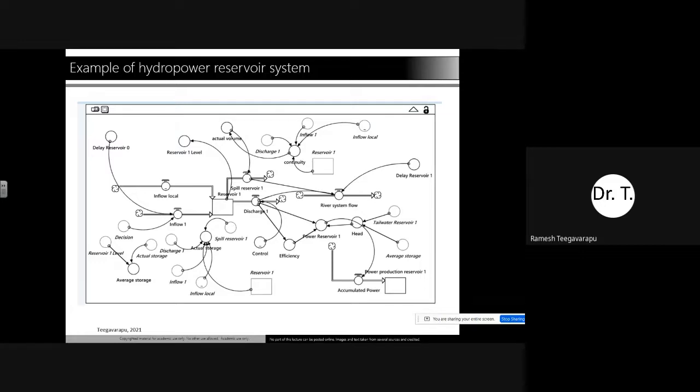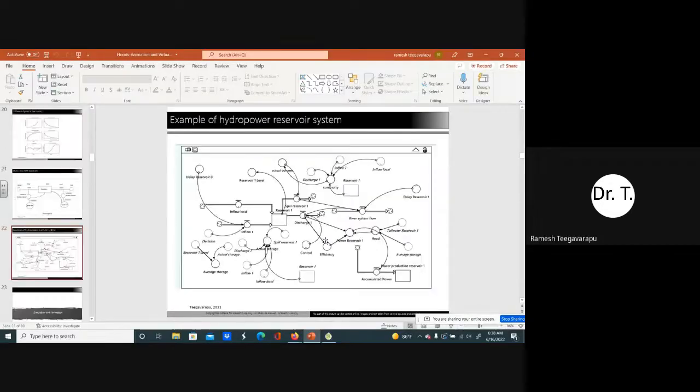Similarly, a hydrologic system can be simulated. You can simulate anything. The beauty of system dynamic modeling is that you are not limited to the specific objects you get in HEC-HMS, HEC-RAS or WEEP. You have these four completely fundamental generic objects: stocks, flows, converters, and connectors. You can take them and build them into a beautiful model where you can simulate the system. So I want to show you a quick example of that.